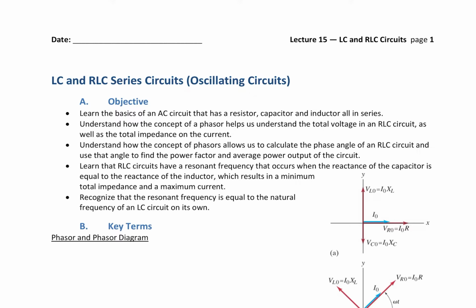Because that's a way for us to quantify power. We're always interested in power if we're talking about circuits. We want to learn that RLC circuits have a resonant frequency that occurs when the reactance of the capacitor is equal to the reactance of the inductor, which results in a minimum total impedance and thus a maximum current. And finally, we want to recognize that the resonant frequency is equal to the natural frequency of an LC circuit on its own. That's really as much as we're going to talk about LC circuits.